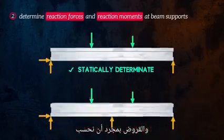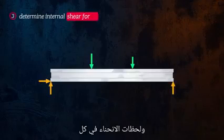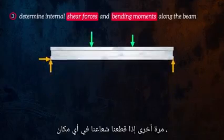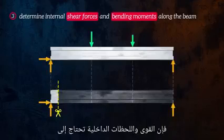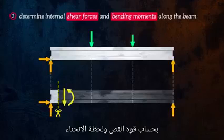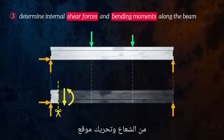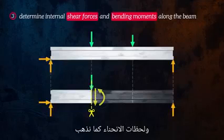of the reaction loads. Once we have calculated all of the reaction loads, the third and final step is to figure out the internal shear forces and bending moments at every location along the beam. To do this, we will use the concept of equilibrium again. If we cut our beam at any location, the internal forces and moments need to cancel out the external forces and moments so that equilibrium is maintained. This allows us to easily calculate the shear force and bending moment at each location along the beam. All we need to do is start from one side of the beam and move the location of the cut along the beam, calculating the shear forces and bending moments as we go.